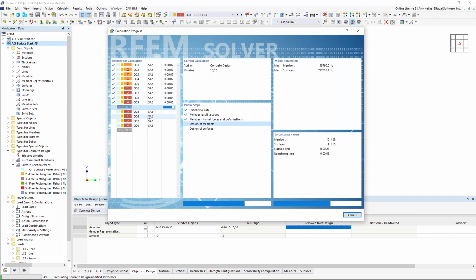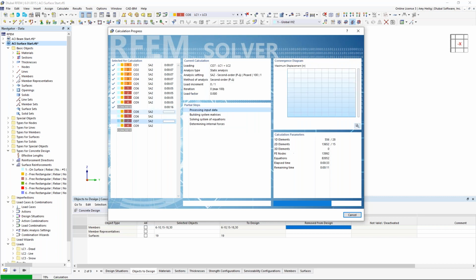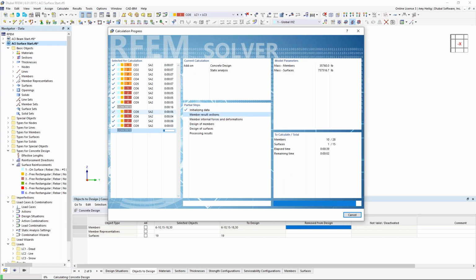Now notice under the concrete, we have to solve again all of the unfactored load combinations. And the reason for this is, remember, we talked about the effective moment of inertia, I sub E, and that is related to the ACI table 24.2.3.5. The program automatically calculates that stiffness reduction to be considered for the serviceability deflection checks. So that's why we're seeing those load combinations listed again here.